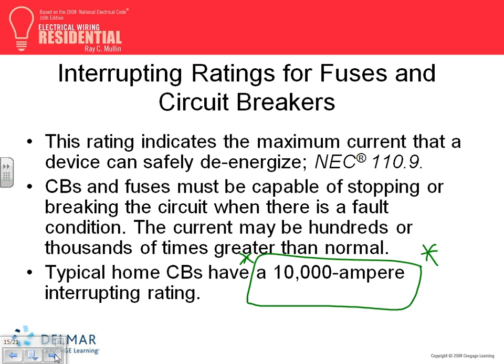For circuit breakers, guys, I believe, if I remember right, if it's rated 5K or less, fine, but if it's more than 5K, then you have to list it. For example, most of the residential stuff, if you read through these, is going to tell you most of them are 10K. What does a 10K mean? If I short anywhere here, this circuit breaker can handle up to 10,000 amps. What happens if you put 20,000 amps in it? Blow up. Very, very simple. So that's the maximum current the circuit breaker can do safely, I emphasize the word safely. It will de-energize, but not before it blows up.